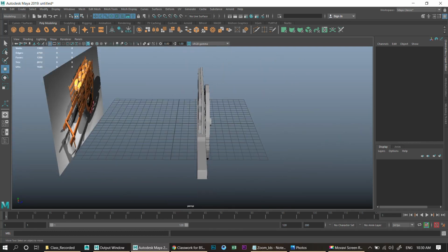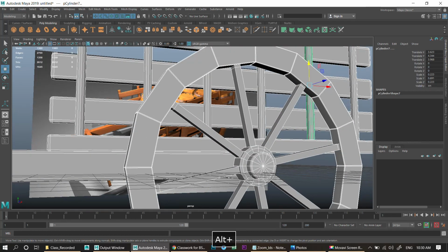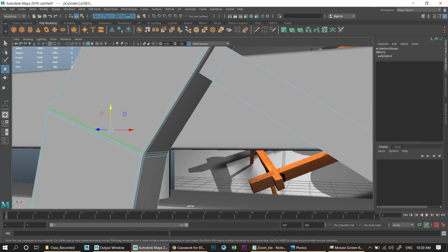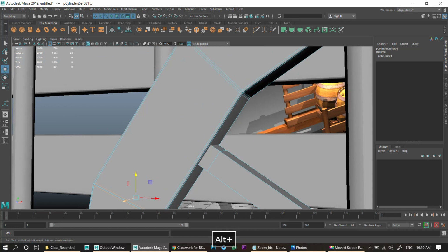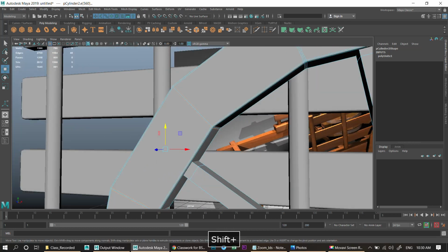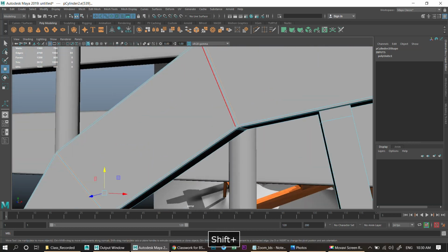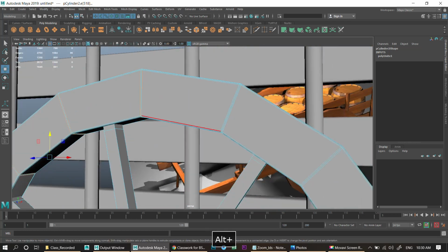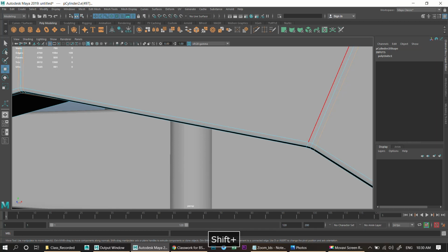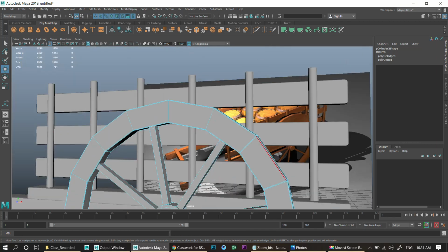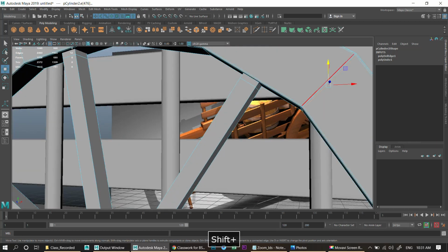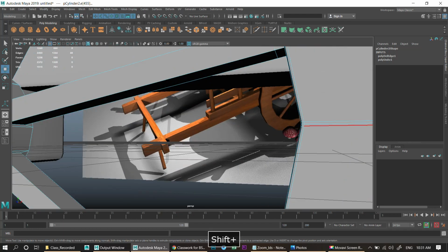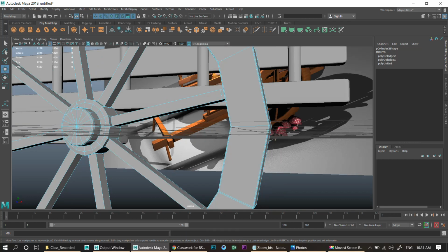Anything else left for this side? No. Here we did one mistake. We beveled from overall, so it created extra unnecessary lines here. So this you can delete, or else you can immediately create one more new. It won't take much time to create. This is actually extra. Delete the edges. It was created by mistakenly applying the bevel, so I don't want that. You can delete it or else just recreate that shape. It's very quick.